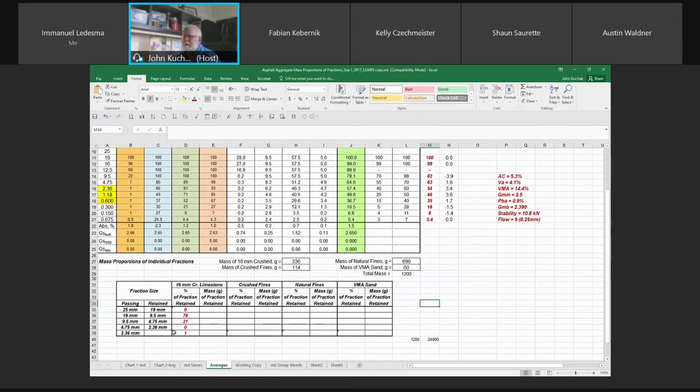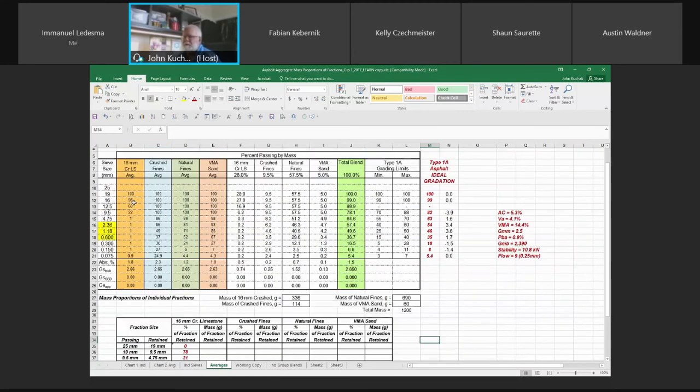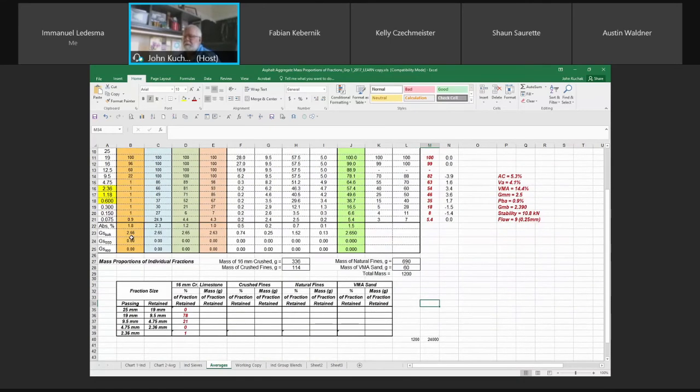So this tells me that we need to go to this 16 millimeter material. And once we've separated that material into these fractions, you physically would sieve it. Like I said, when we have our practical lab in B109, we've got dust all over the place, because crushed limestone is dry, with lots of crusher dust in it, and it's just all over the place.